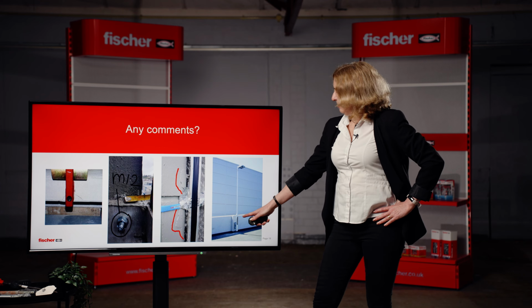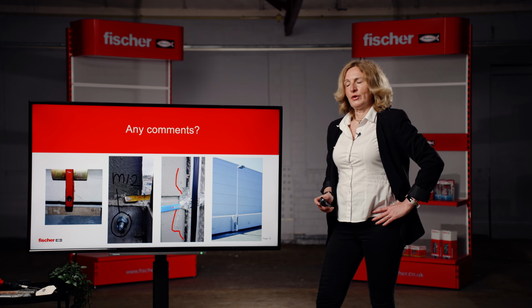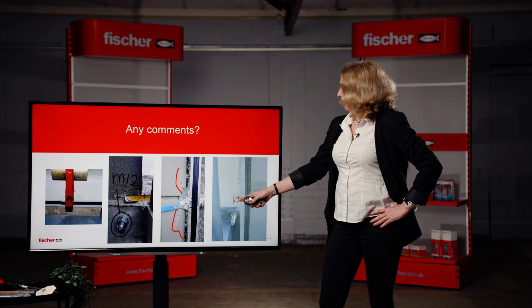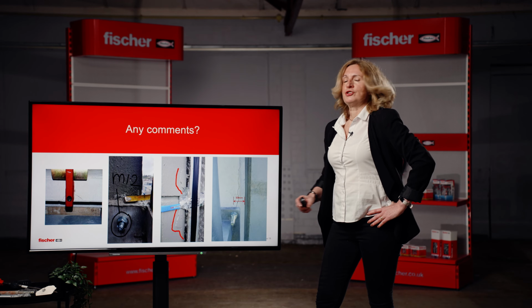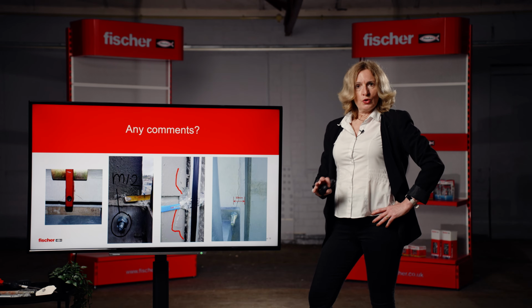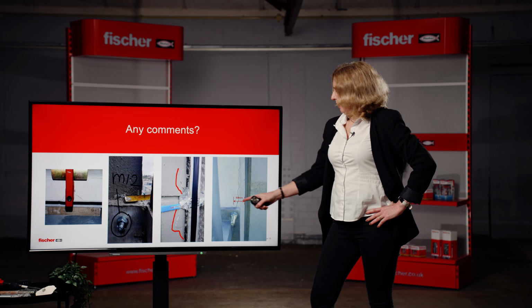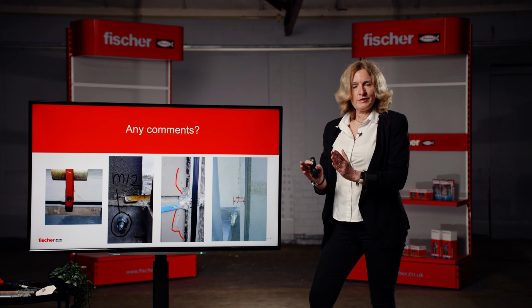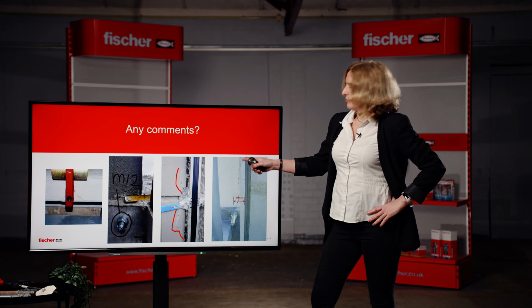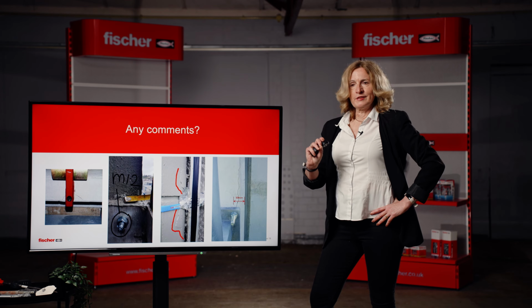And here as well, if you look at this lamppost connection, when we zoom in, you will see the damage to concrete due to small edge distance. This was a 16 mm diameter torque control expansion fixing, installed only 50 mm from the free edge. So no surprise, big damage to the substrate was done during installation.